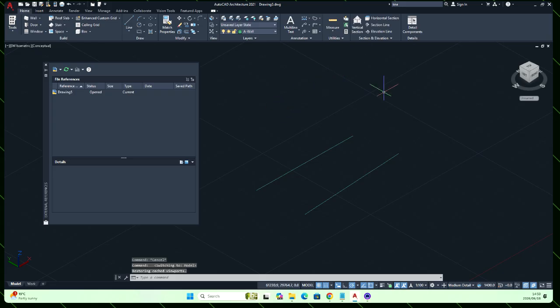Grid is the lines you see here in the background. You can turn that on and off. Snap is if you move this item somewhere, you can see that little green box that pops up. That's snap. So it's snapping to that. So if I move close to it and it highlights and I click, it snaps to that. Okay. Ortho mode. Obviously, if you draw in ortho mode, it's 90 degrees, so you can set it actually. But ortho mode just works on a 90-degree. See that it snaps to